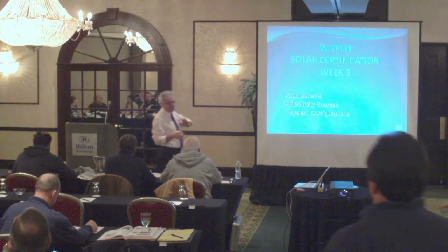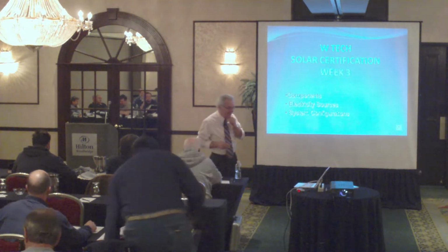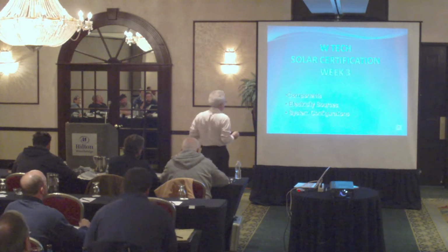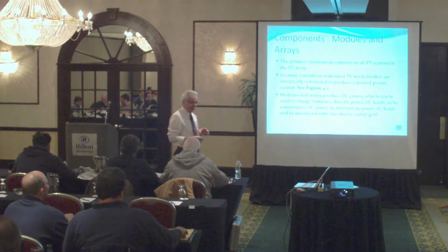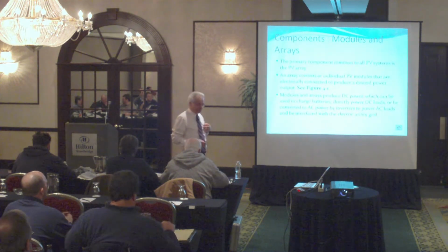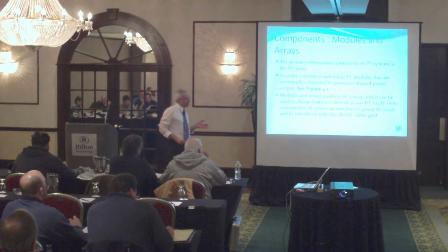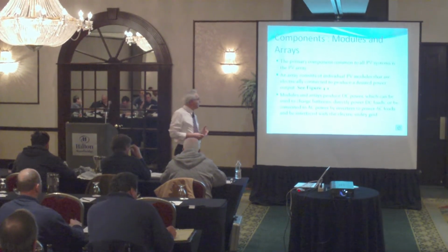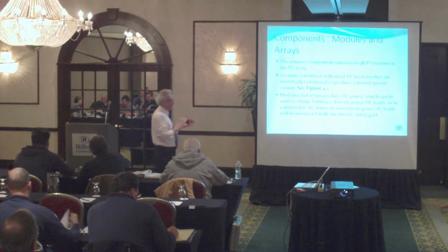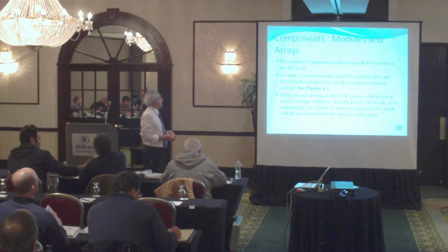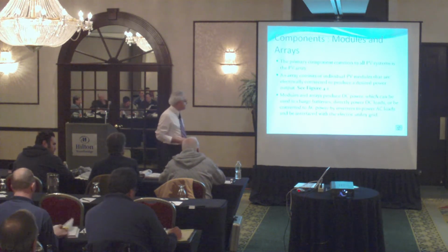We'll talk a little bit about the components, the type of sources we have, some of the systems configurations now. Main component in a solar system is what? The array itself. Typically, you have individual modules. You hook them together in series or parallel methods, and you get a certain type of output out of the actual array.